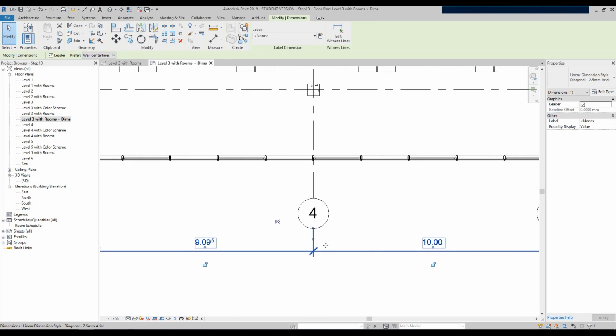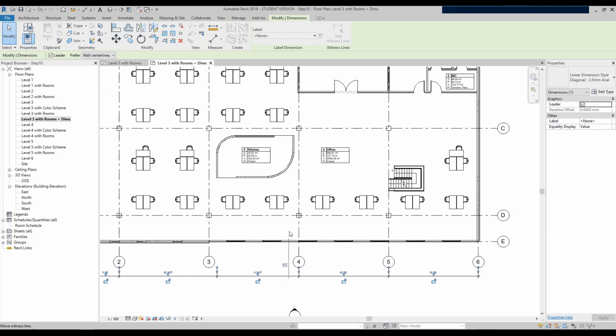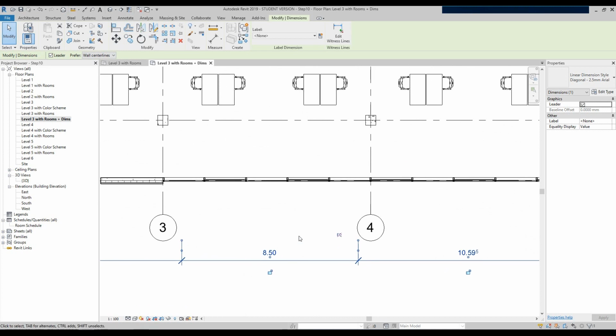Then go down to grid line 4, the dimension, the bottom little spot which is closer to you, south of the drawing. Click once but hold your mouse button down, go up to the other kitchen wall and then release. You will notice that our dimension has been updated.